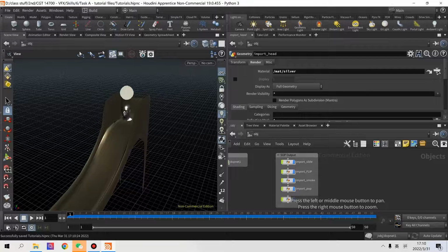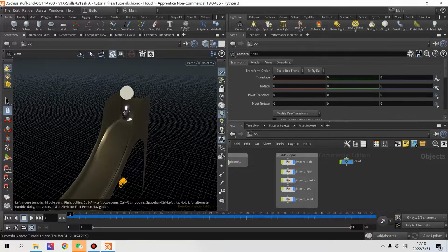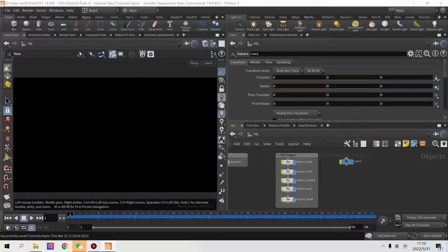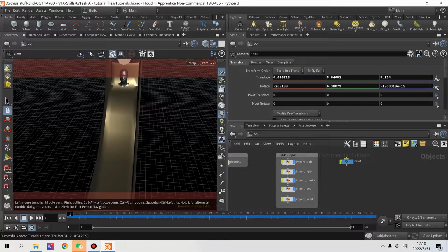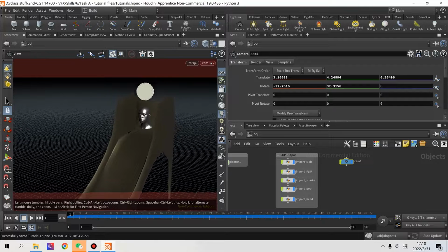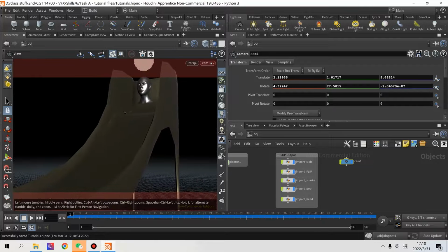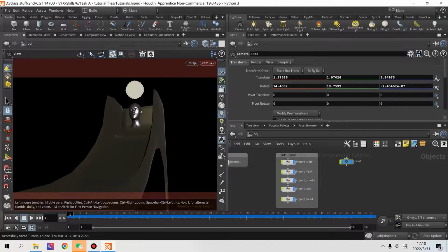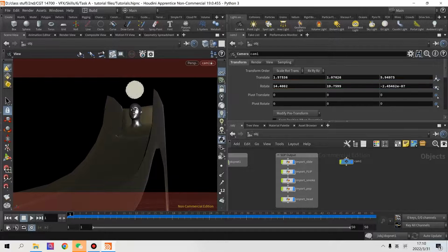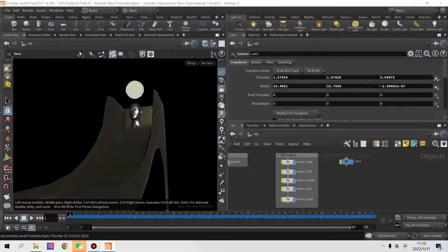So before we actually render it, we need to do some necessary things to set up the scene, which is camera and light source. For the camera, we're just gonna add a camera to our object interface, and we can see a little camera here. And we can select the camera views through this button. After clicking that lock button here in the middle, we can just control where the camera will move according to our movements, and we can set it somewhere perfectly precise without using all of the translate and rotate values up here in the parameters. So we have something like that, which is pretty good.